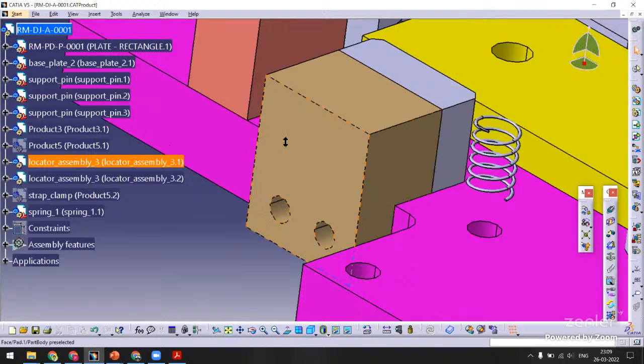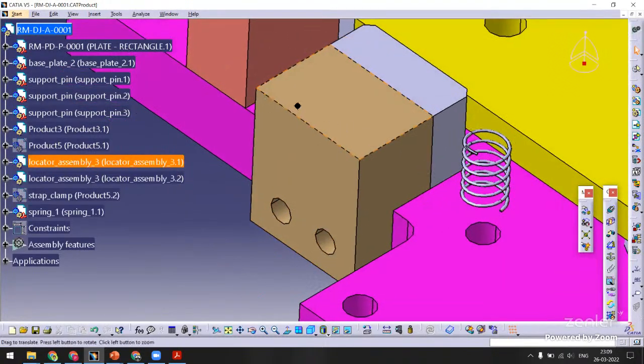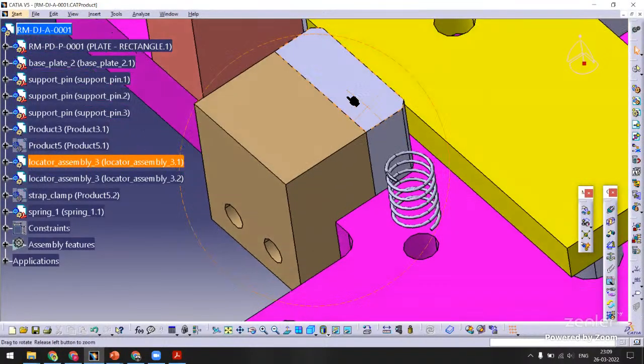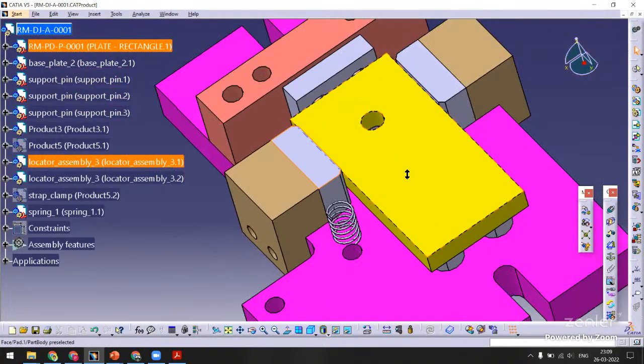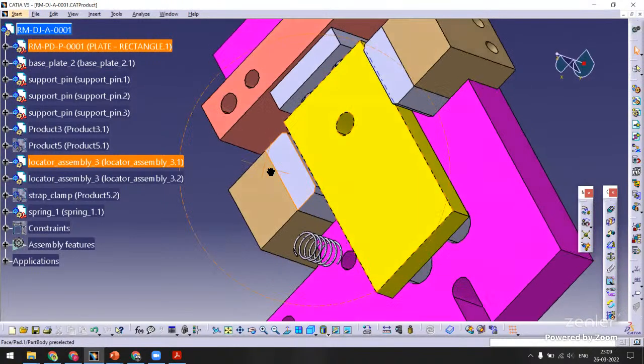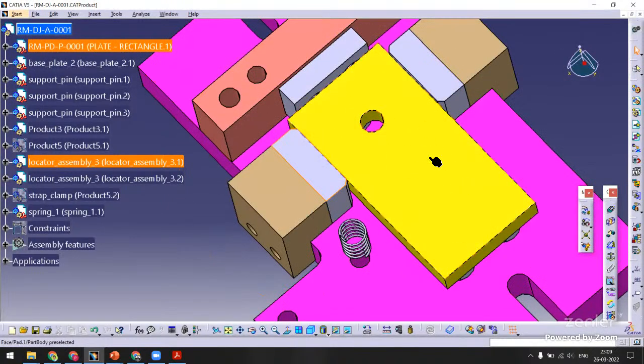Why have I designed it like this? What am I trying to do? Basically, what I have here is called a wear plate. When we are loading and unloading the workpiece, hundreds of them, the tendency is that this will wear out, because it is metal to metal, hundreds of times, adding it, removing it, or in other words, loading it, unloading it, loading it, unloading it. So we want this to be hardened, really harder than the workpiece, so that it doesn't wear very easily. So I made it as a separate piece.